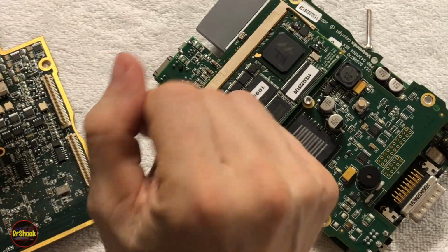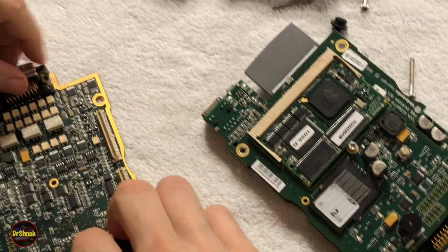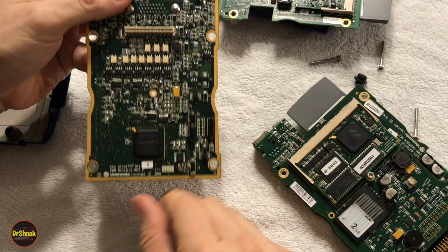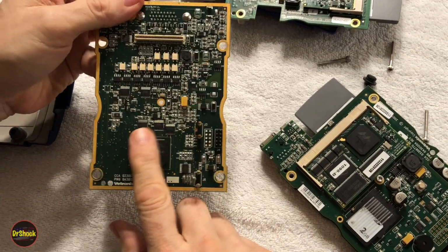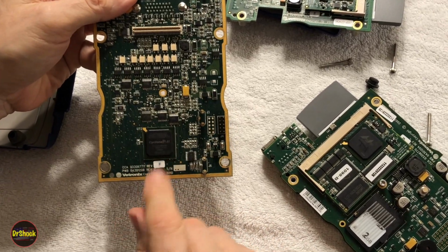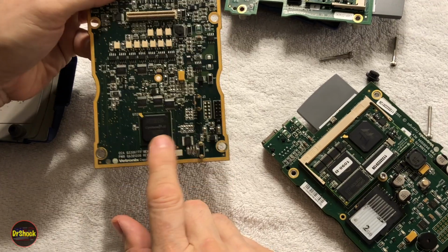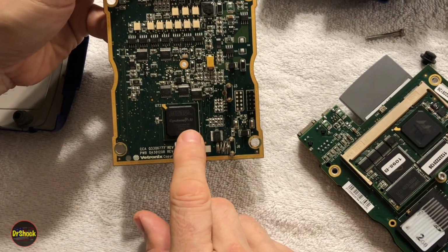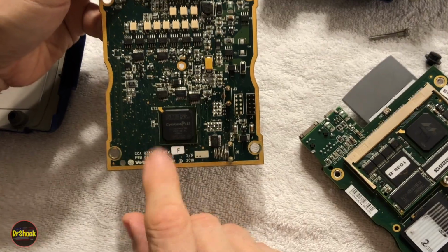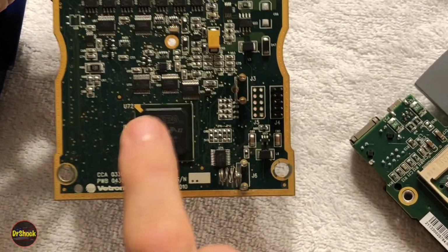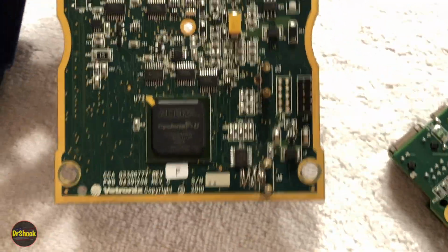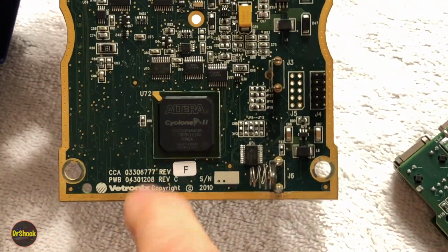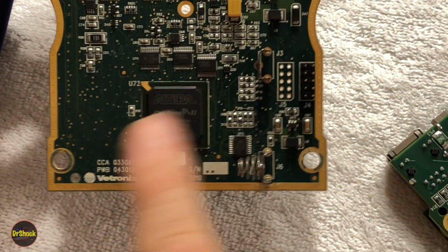The only other thing I'm going to do in this video is we will take a gander at seeing if we can bring one of these back to life by reflowing one of these. It's not a repair, right? Because it's very rare that the problem is actually a broken solder ball. It's more often than not either the problem is internal to the die of the device and you need to actually replace it. I mean, these are not like graphics cards in a PC where it's very common to reball and do a repair.